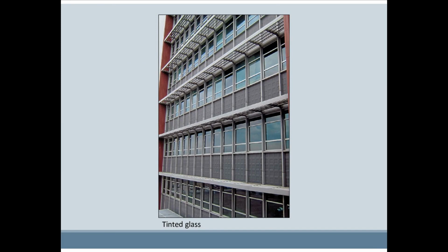Some post-World War II buildings were glazed with tinted glass originally. When the color of the glass was part of the architectural design, any replacement windows or new glazing must be consistent with the historic appearance.